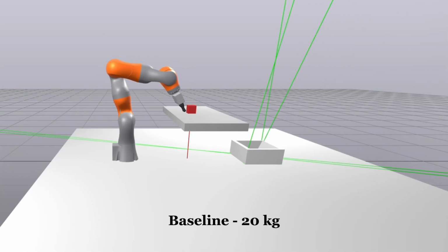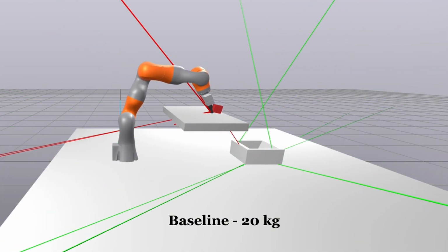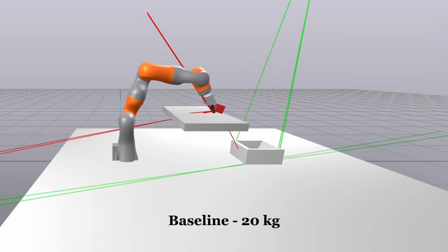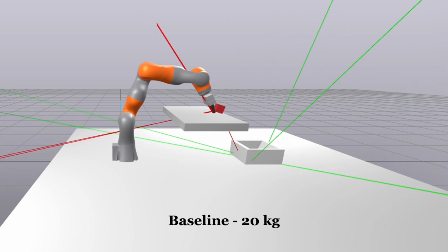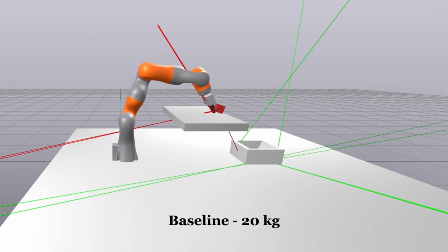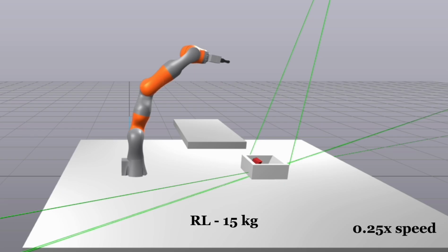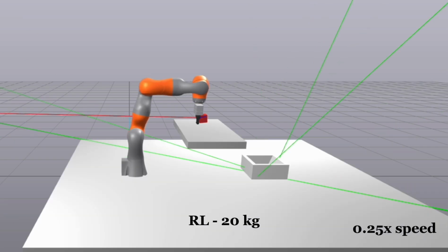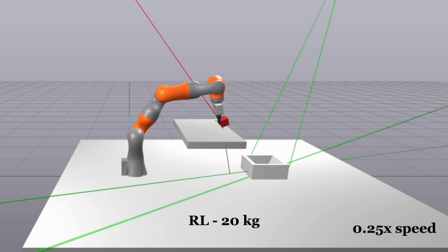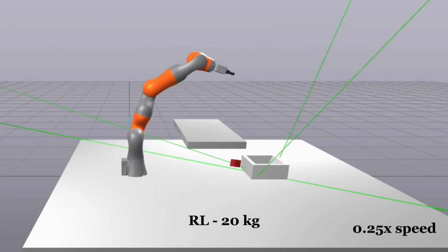The baseline controller struggles on masses that are above 16.5 kilograms and the box falls short of the bin or does not make it past the table. However, the worse performance is expected since the approach does not account for the differing mass. The RL approach also struggles on larger masses. One explanation is that the robot's range of motion is restricted by the joint locking mechanism. Better tuning of the reward function would also incentivize the algorithm to not enter a local minimum.